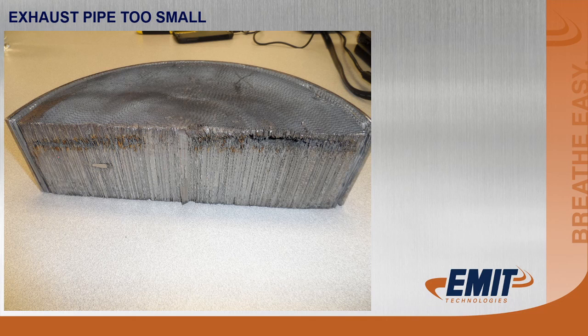Here's a catalyst. I actually damaged this catalyst myself. This was on an 817 Waukesha, and the customer had built their own exhaust piping. The unit had failed in its emissions test. I went out there to take a look at it, and it had a brand new catalyst element. I took their catalyst element out, which only had an hour or two of runtime on it, and I put this catalyst element in, and it was passing fine for a few minutes, and then the numbers began to deteriorate.